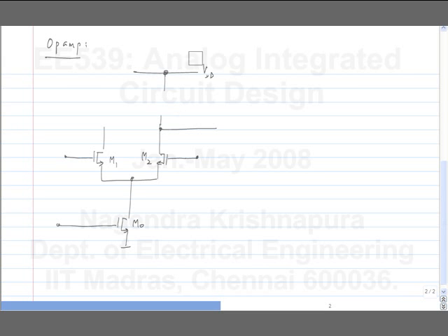So we decided to replace this with a MOS transistor, which can carry the same current, but give you a much higher resistance in the incremental sense. Okay, it gives you a much larger resistance. In quiescent condition, I naught by 2 has to be flowing through that, and perhaps a convenient way of getting that I naught by 2 is by mirroring this one. Okay.